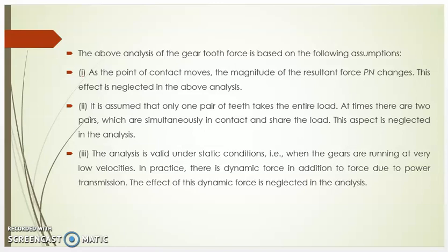Third, the analysis is valid under static conditions, that is when the gears are running at very low velocities. In practice, there is dynamic force in addition to force due to power transmission. The effect of this dynamic force is neglected in this analysis.